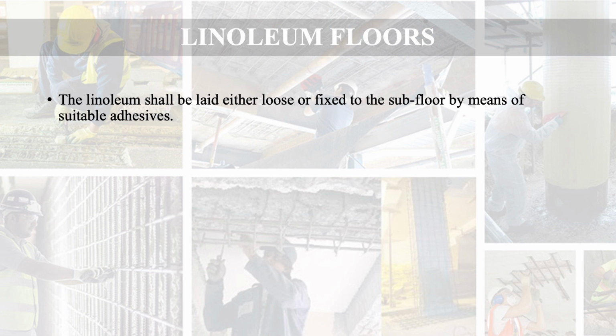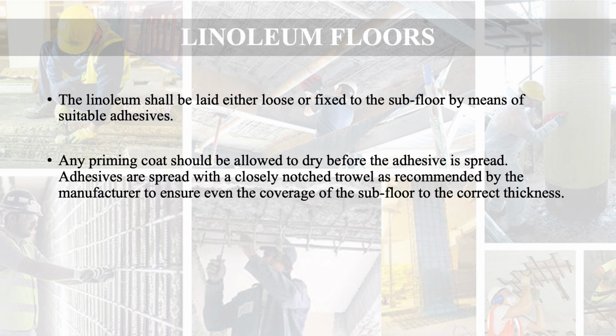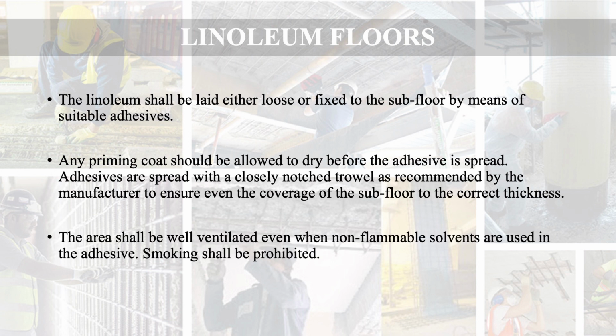Linoleum shall be laid either loose or fixed to the subfloor by means of suitable adhesive. Any priming coat should be allowed to dry before the adhesive is spread. Adhesives are spread with a closely notched trowel as recommended by the manufacturer to ensure even coverage of the subfloor to the correct thickness. The area shall be well ventilated even when non-flammable solvents are used in the adhesive. Smoking shall be prohibited while doing this type of flooring.